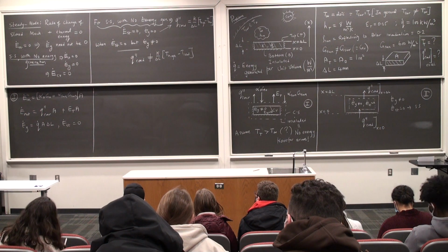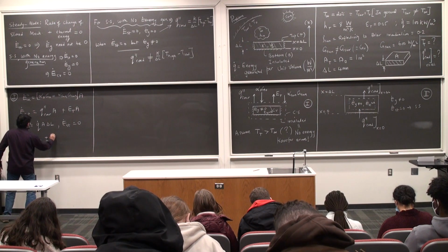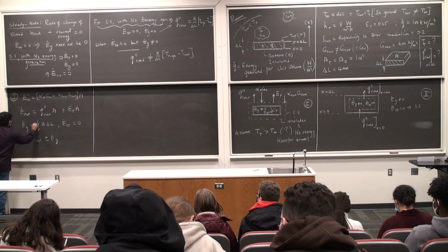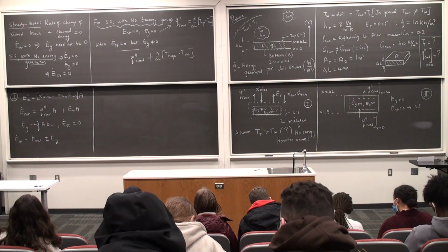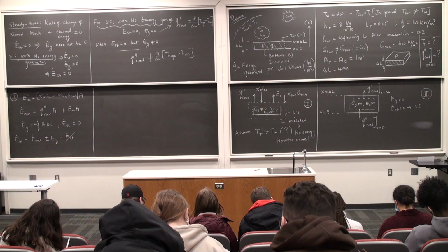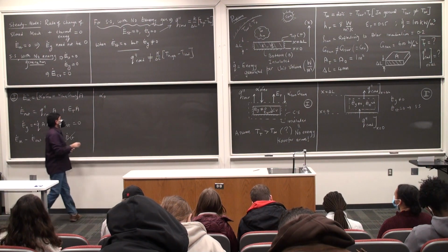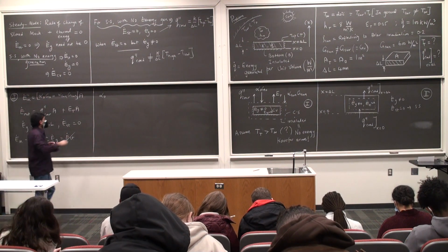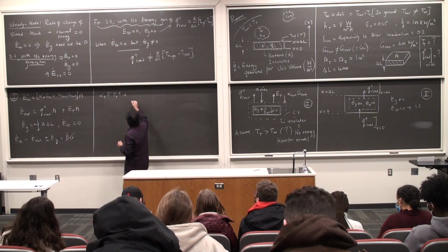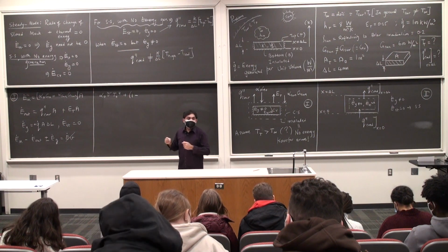Write your energy balance equation. E dot in minus E dot out plus or minus E dot generated. In this situation, you are told in the problem that this is a positive heat generation taking place. So I'm going to put a positive sign there. This is equal to E dot stored, which is 0. E dot G is positive for us, so I'm just going to write down all these terms. So alpha naught G naught, which is sigma times T naught to the power 4, plus alpha of the sun, which is known to me because I'm given the reflectivity of the surface to the solar radiation, this is going to be 1 minus rho of the sun.